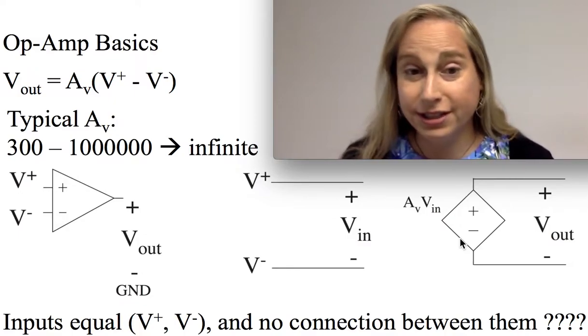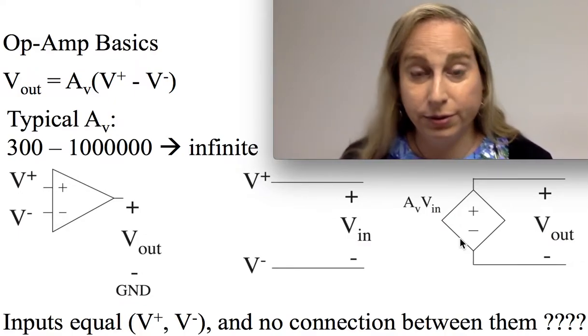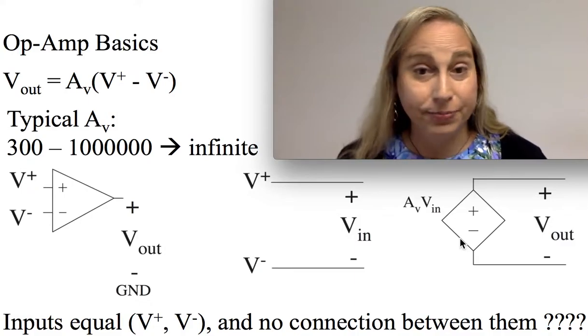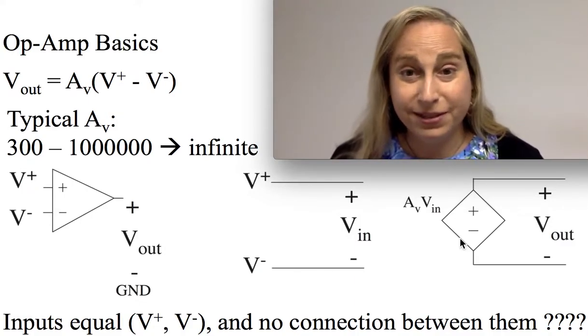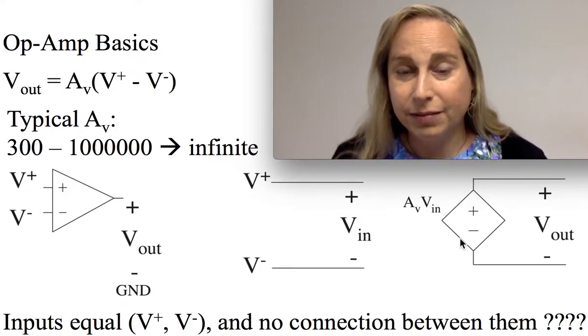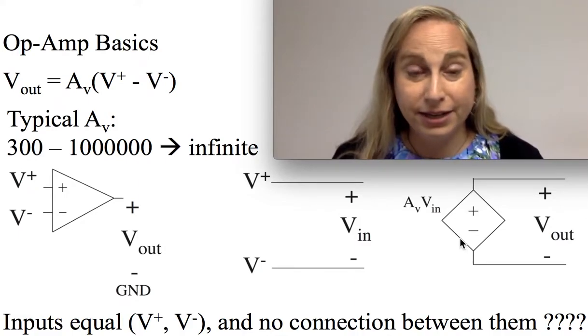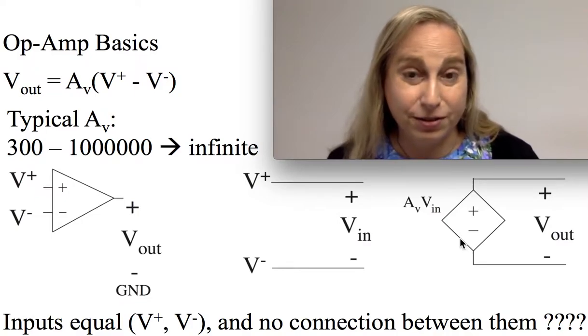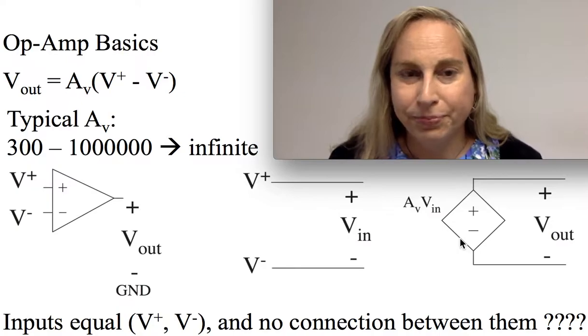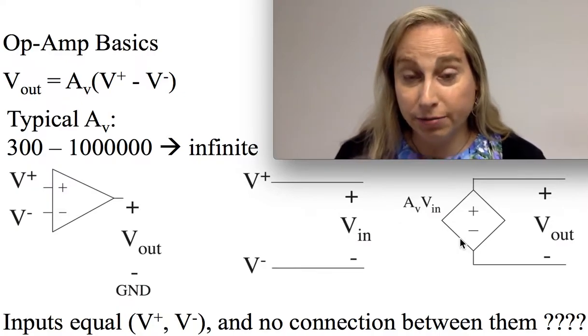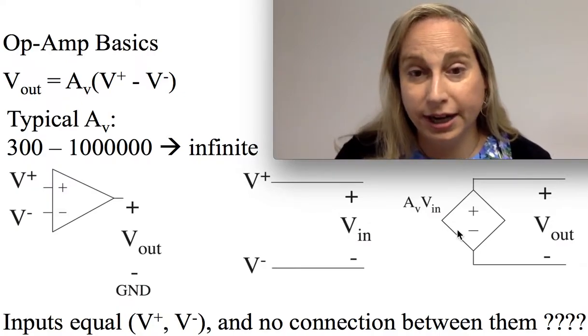This structure gets thought about in multiple ways, one of which is as just a high gain amplifier. Another way to think about it, which we'll talk about a few other times, is that it feels like an integrator. It has a high gain, but that's often at very low frequencies, though we might just approximate and say it's a high gain everywhere. That's typically the starting model when you start with this structure.